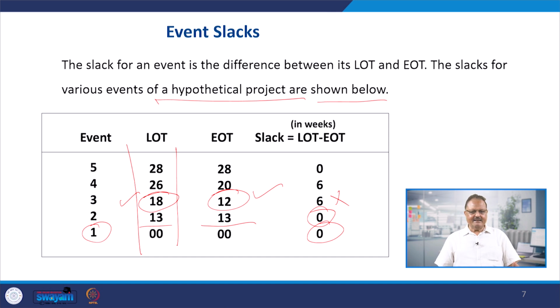So normally while developing the networks, we use the critical paths, not the slack paths, and there we try to use the minimum time period which can be estimated for completing different activities and consequently the whole project. And there we want to find out which activity or event has the slack, and how that slack can be understood in advance, taken care of, and removed, so that finally the network which we are going to develop is the longest path, not the shortest path.